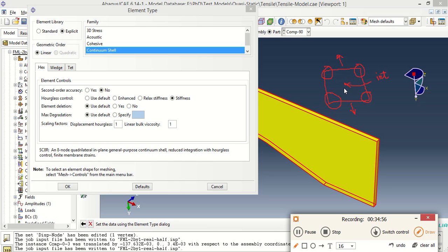So your data is calculated only at the integration point, but this is not the exact data. If your element is large enough, there will be some deformations here that are not captured by the integration point. Your element is deformed, but your integration point doesn't feel that deformation, and your stresses and strains don't feel it. So there is an error in the calculation.